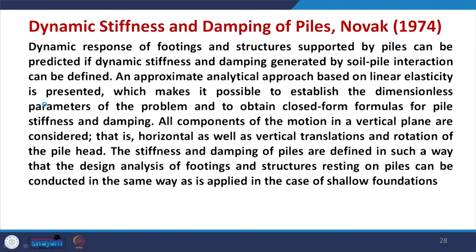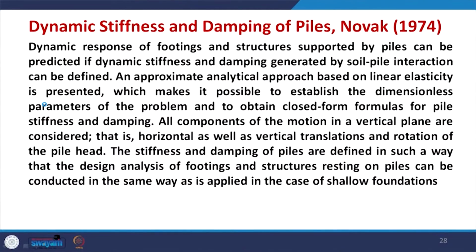What we are going to discuss is from a very famous paper by Novak in 1974, which is published in Canadian Geotechnical Journal, and perhaps this is the first publication on pile group for the systematic study considering the continuum, that means considering the radiation condition as well as inertial effects. So, in this case dynamic response of footings and structures supported by piles can be predicted if dynamic stiffness and damping generated by soil pile interaction can be defined.